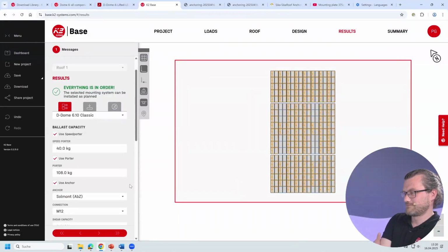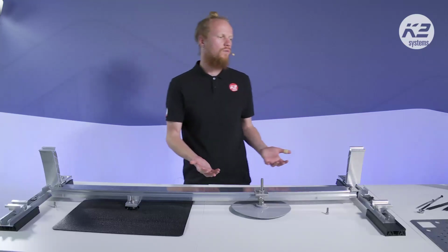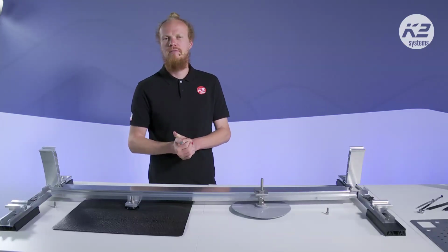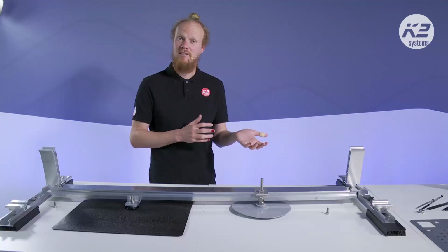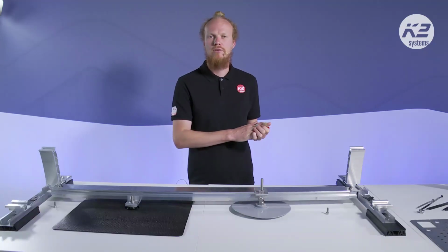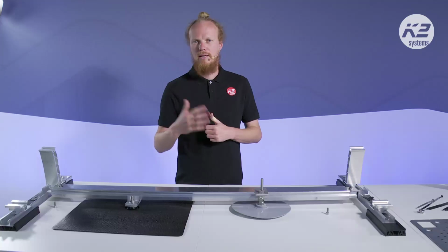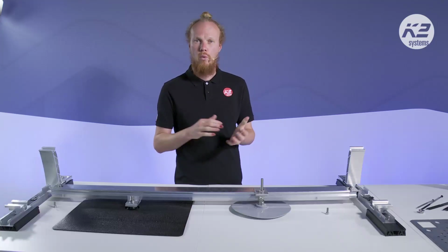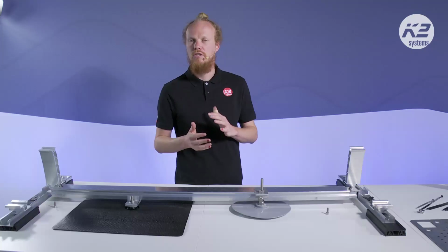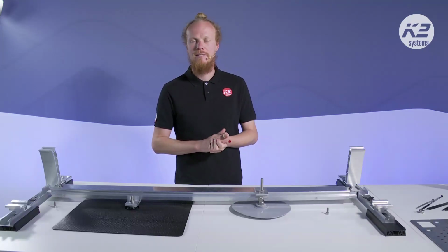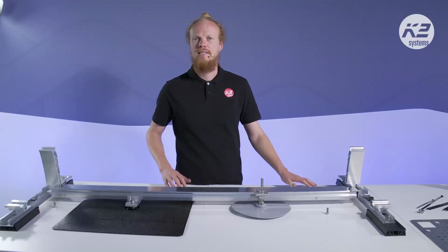We also had a question about the east-west system for maybe a roof over 10 degrees. So this is more of a choice question from an energy production perspective. There are two parts to putting PV on a roof: how much energy you want to produce, and how easy it is going to be to put the PV on the roof. For flat roofs, you would increase the inclination in one direction, whether south or east-west. This gives you flexibility to determine how much energy you produce, depending on the time of day and your own needs. You can just place it on the roof, generally speaking, ballasted down or with the anchors that we've shown today.